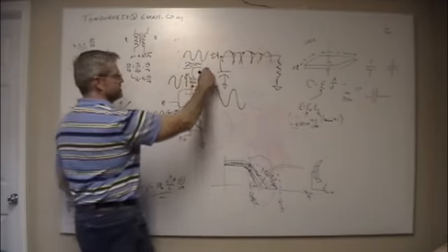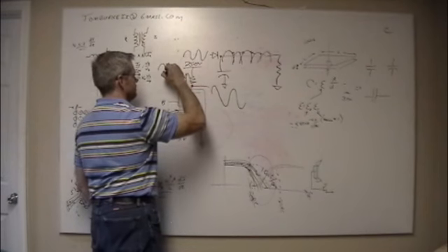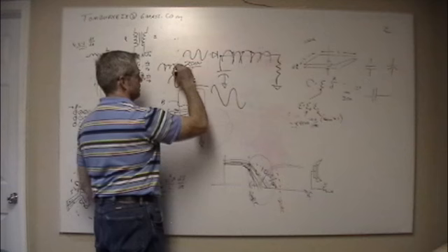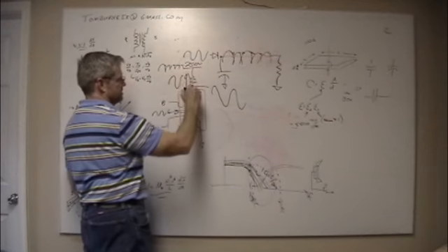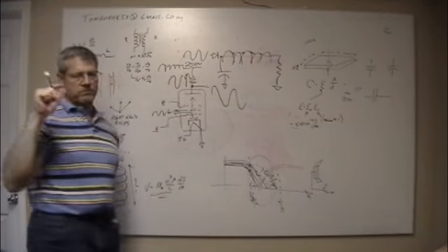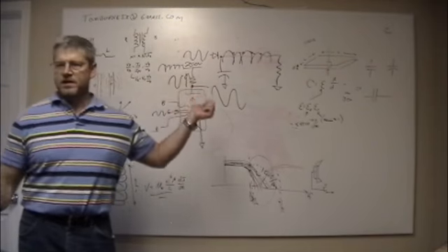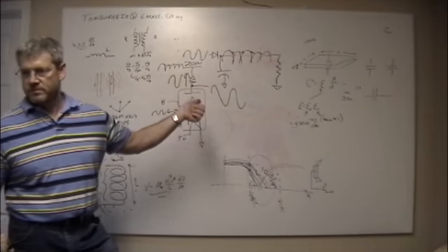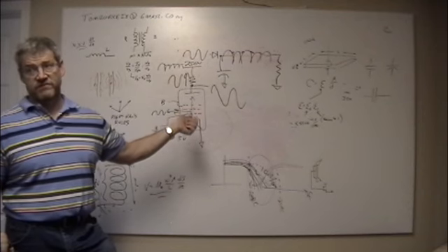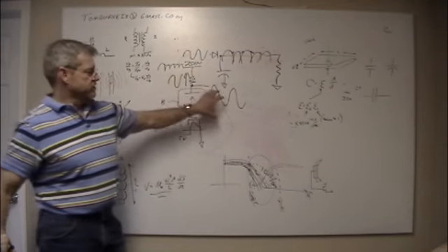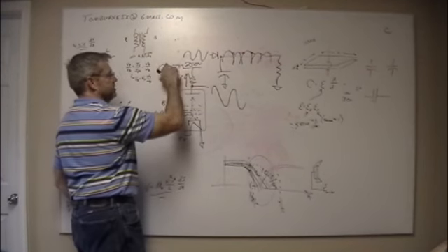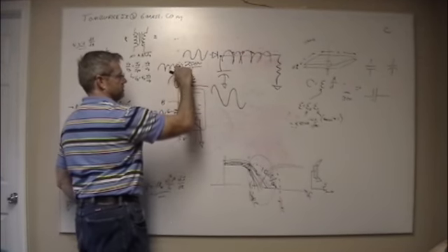Practically speaking, though, this is up here on your power, and your power is doing this. So it's pretty level. If that's only a volt out of 200, if that's 2.5 volts, if that's a 1% ripple, 2.5 volts out of 250 isn't very much. And so there's not any real big effect here. But if that capacitor's blown,